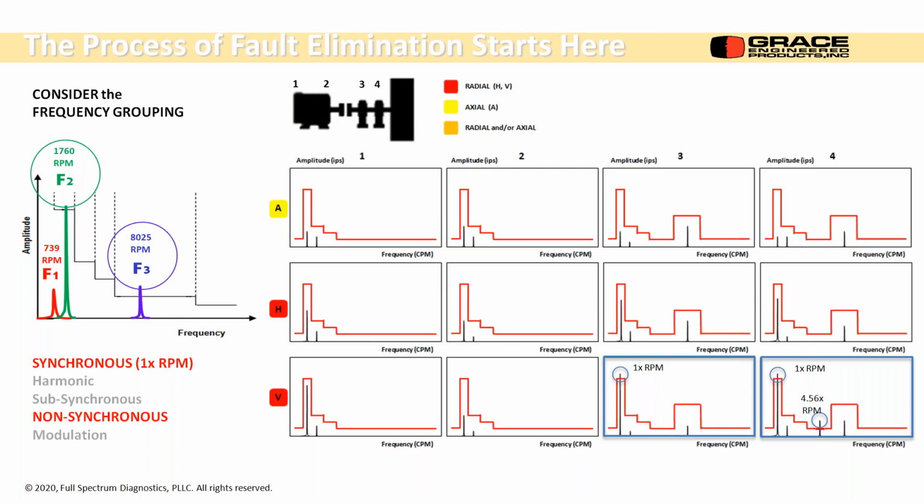Okay. Is there ever a blade pass frequency for a TEFC motor which has an integrated cooling fan? No, those cooling fans are plastic usually. There's two different types. The cooling fan in a squirrel cage motor or a cast motor, the rotor will have protruding fins on it, and as the rotor spins, it'll act as a fan, and that's what they're kind of designed to do.